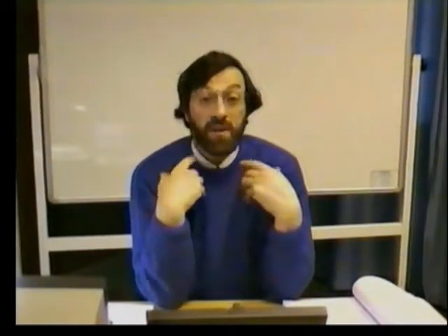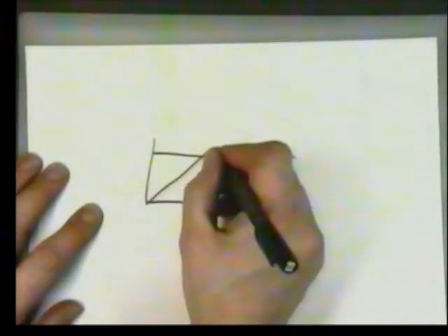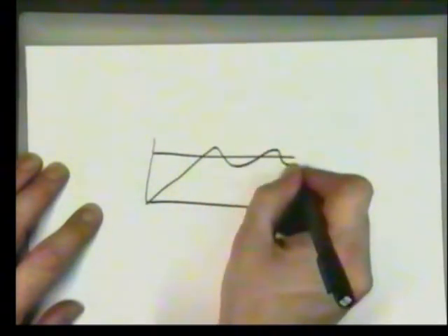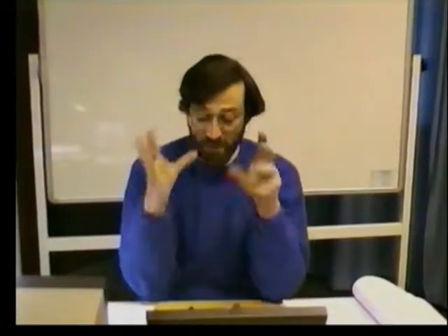One of the simplest structures there is, and very widely used. And why not? If it works, let's use it. All we say is that if the measured variable is below the set point, we switch on. And if it's above, we switch off. And we get our characteristic response of rising up and then oscillating nice and gently around the set point. But the danger with that is that if your response is too quick, you can have very, very high speed oscillation. So to overcome that,